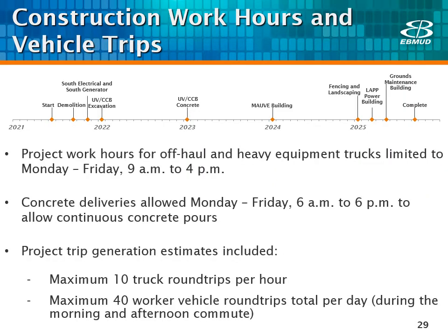To proceed with the traffic analysis, we needed to determine project work hours and estimate the vehicle trips generated by the project. For the project, we are limiting off-haul and heavy equipment trucks to Monday through Friday between 9 a.m. and 4 p.m. This allows this construction traffic to avoid the morning and afternoon peak commute times. However, concrete deliveries will be allowed Monday through Friday from 6 a.m. to 6 p.m. to allow 12-hour continuous concrete pours. This is because disruptions in concrete pours can affect the quality of the concrete work and service life of the structure.